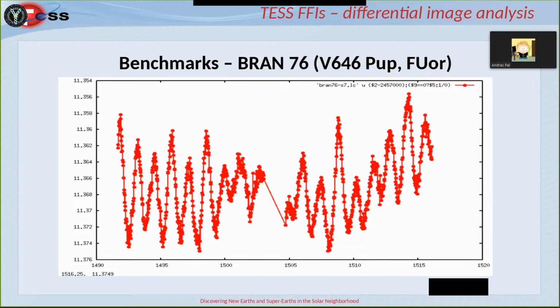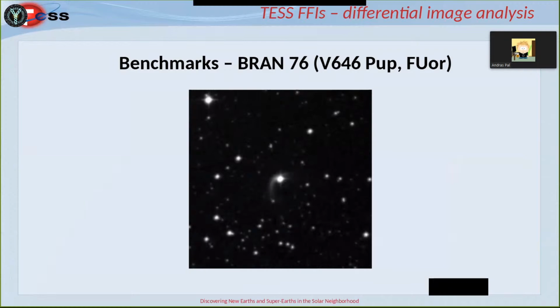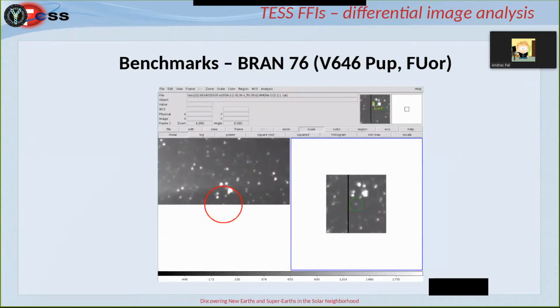Because of this pointing of the satellite, so changing in its attitude, would result in different temperature distributions in the detectors. There is also an additional reserve of a few hours until the thermal equilibrium is reached, which also minimizes the side effects of the variation in instrumental characteristics.